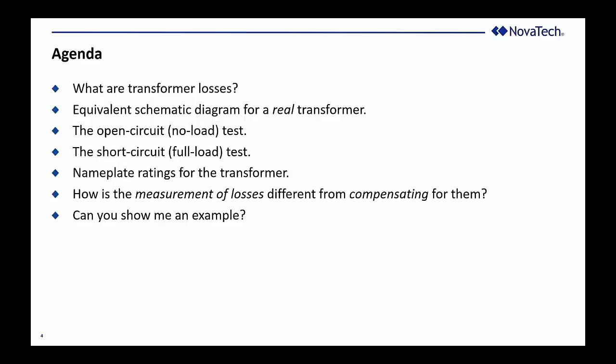We'll focus on two performance tests, the open circuit test and the short circuit test, which reveal the characteristics of the transformer, which permit you to do loss compensation in the field, assuming that you have a meter that performs loss compensation.